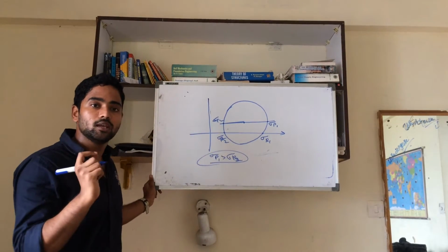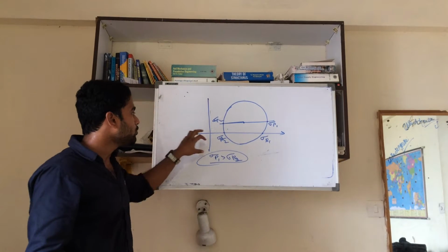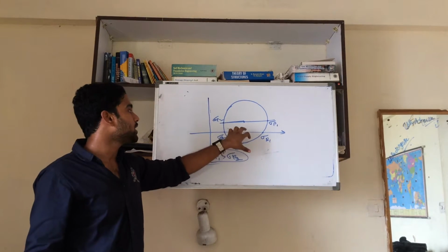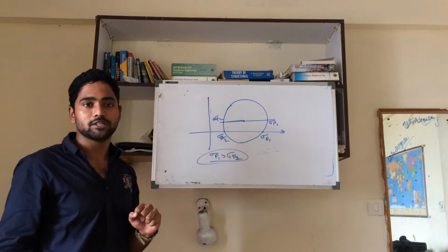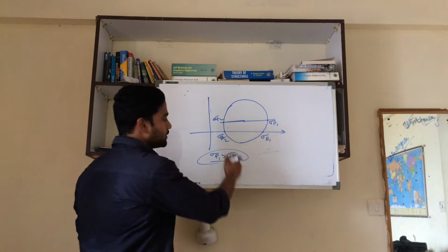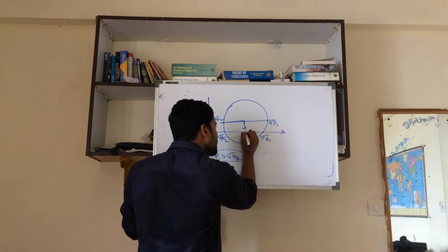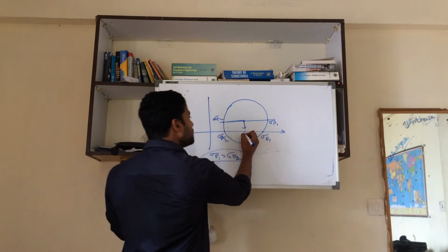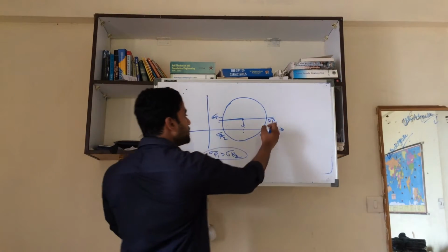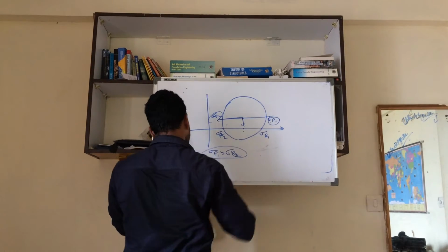According to the theory that I have explained before, the planes on which tau is equal to 0 are the planes where we get the maximum and minimum principal stresses. So that theory is violated over here. Hence, the center has to move onto the sigma axis. So the center will be on the sigma axis, so that sigma p1 and sigma p2 will be the principal stresses. This would be the maximum, this would be the minimum.